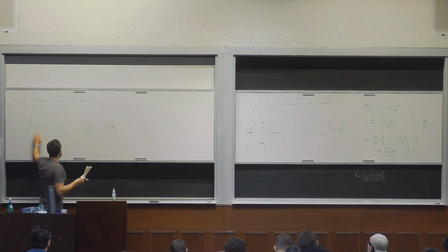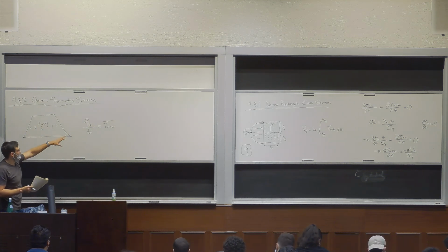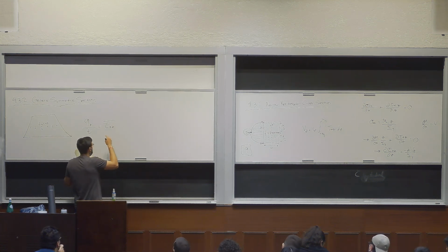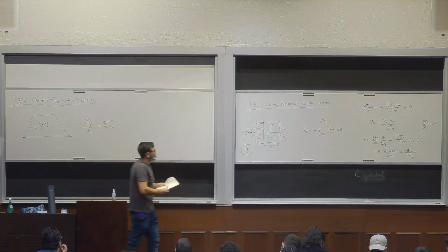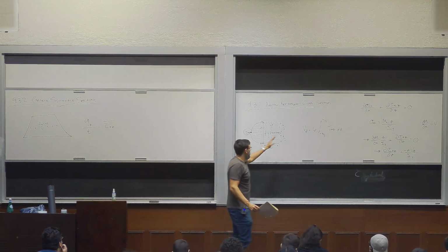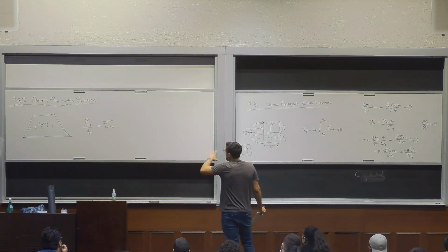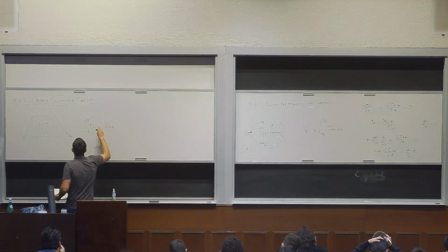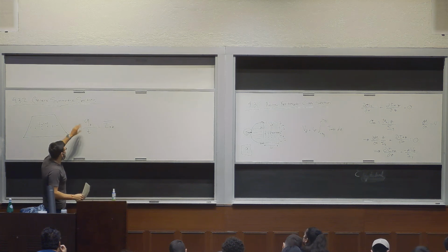If the stress is not uniform, then we add that bar. That signifies that it's the average shear stress, as opposed to without the bar, which would mean that it's constant. Like in this case, tau is constant throughout the y direction, so it's just tau. Here we don't know the distribution in that direction, so we assume an average. In these problems, we're trying to find Q, and the equation is going to be slightly different.